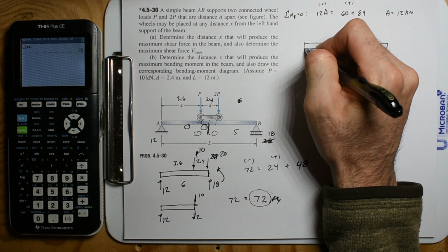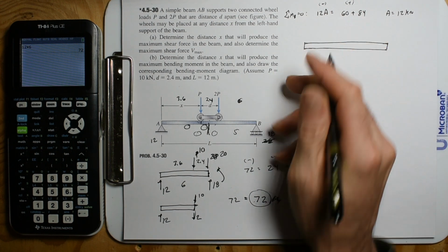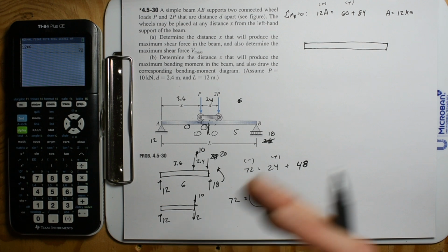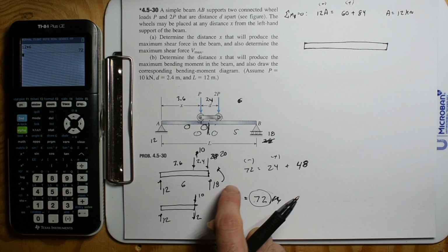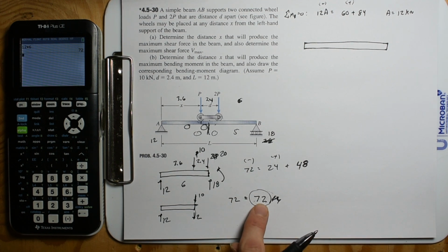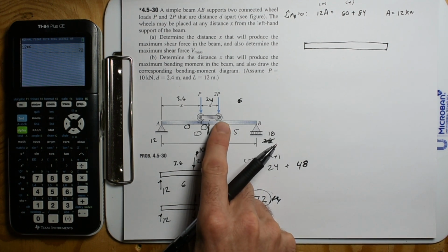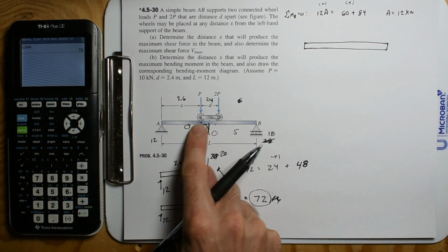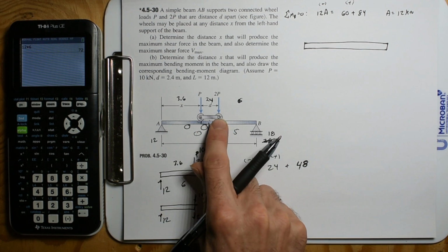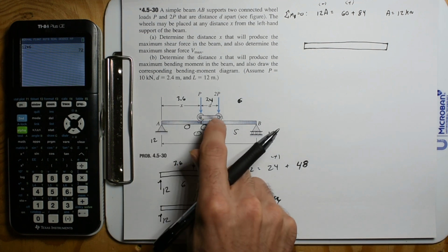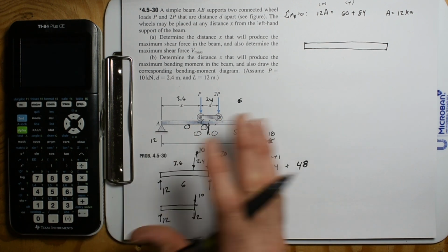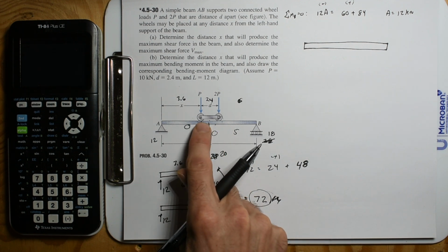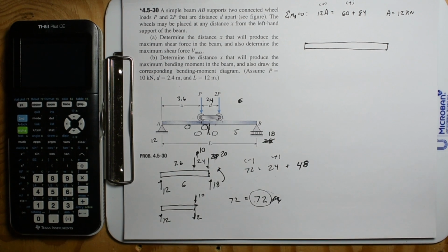I think you can learn a lot from doing methods like this, of just doing the problem over and over again, but in a different way. Because you will find places where your intuition was wrong. You know what I mean? Yeah, that was kind of fascinating, that the biggest moment's going to be under that wheel and not that one. But when we had it over here, the biggest moment was under that wheel. Oh, and so I guess the biggest moment is going to be closer to the center than away from the center. So I guess I get that as well.